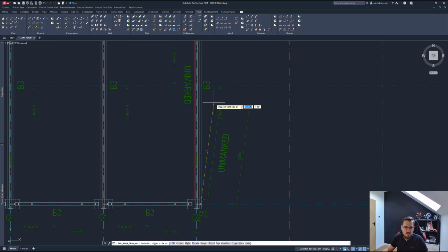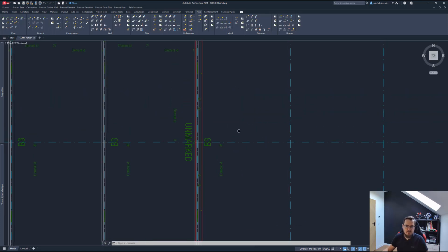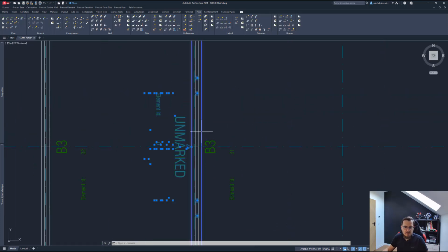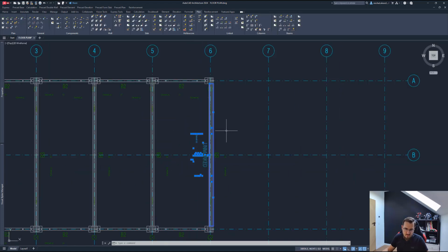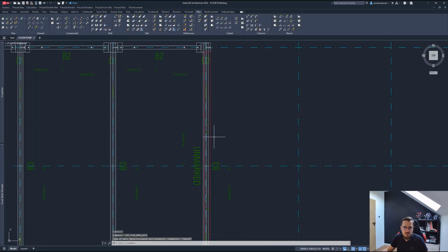You can immediately see, I'll press space for you, that the wall is marked red. That means it's too big. We have settings in Impact. They mention that if an element is too long or too heavy, it will give you such a warning, right? So the warning is red, so something's wrong.